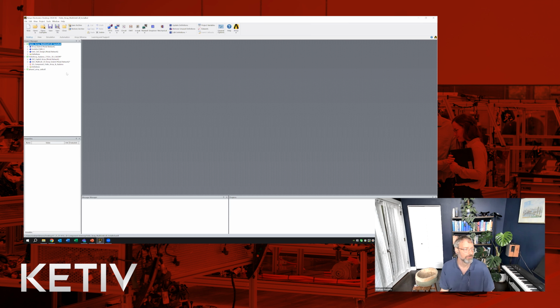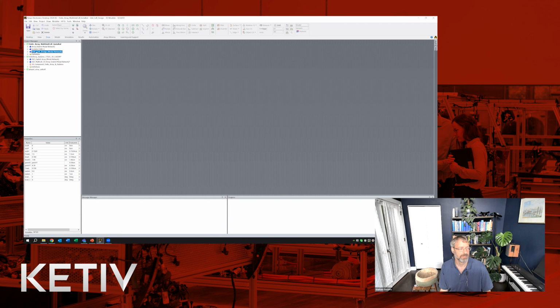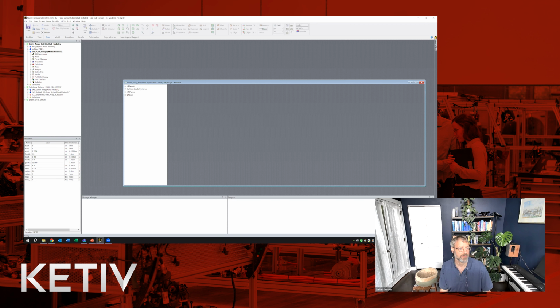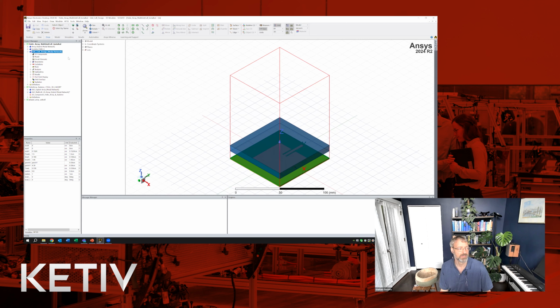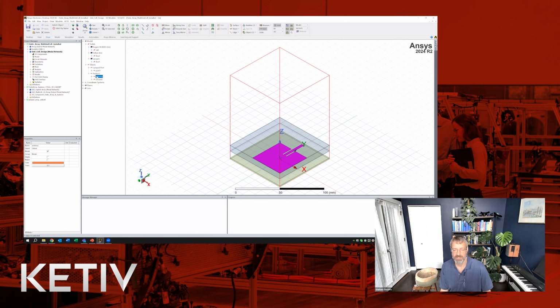And if we shift now to a finite array, we start a finite array with a unit cell design. In this particular case, it's somewhat similar. We've got our substrate here, a Teflon radome piece here, our ports, and a perfect E antenna here.